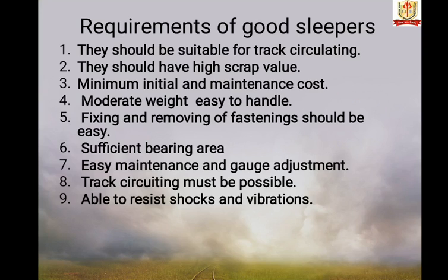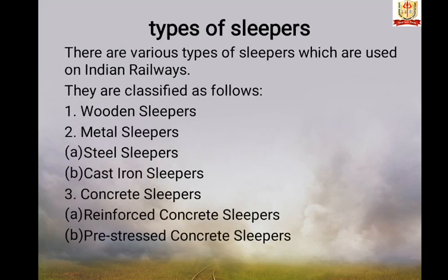Requirement of a good sleeper: they should be suitable for track circuiting. They should have very high scrap value, minimum initial and maintenance cost, moderate weight, easy to handle. Fixing and removing of fastening should be easy. Sufficient bearing area, easy maintenance and gauge adjustment. Track circuiting must be possible, able to resist shocks and vibrations.